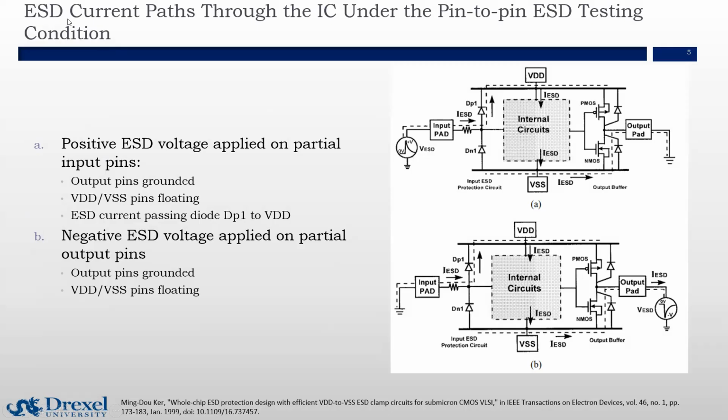In this slide, I'm going to discuss the ESD current passing through the IC under the pin-to-pin ESD testing condition. The positive ESD voltage is applied on partial input pins, with other output pins grounded in this condition. Our VDD and VSS pins are floating.